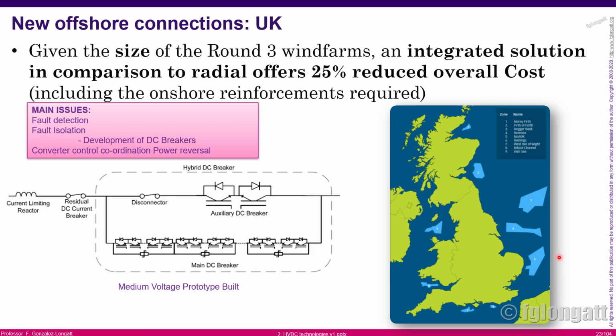Almost to close this, over here, in light blue color, I am presenting 9 different areas where we already have offshore wind power, or are estimated to have it, in GB, okay? And you can identify very big wind farms like Dogger Bank or Hornsea, and we are talking about clusters of wind farms reaching 3,000 megawatts, 2,000 megawatts, okay? The use of HVDC systems and undersea cables will be a key element to consider for the technical solution and the integration of that offshore wind power, okay?